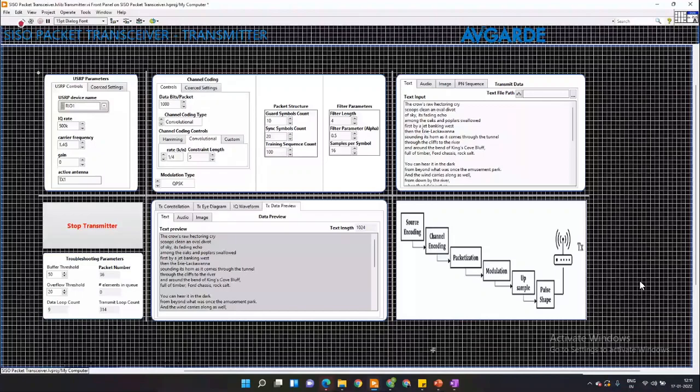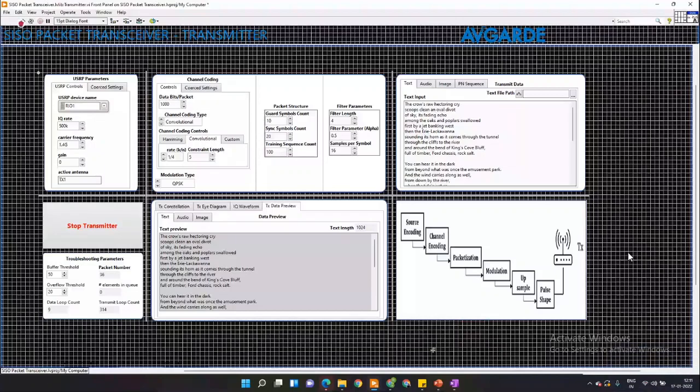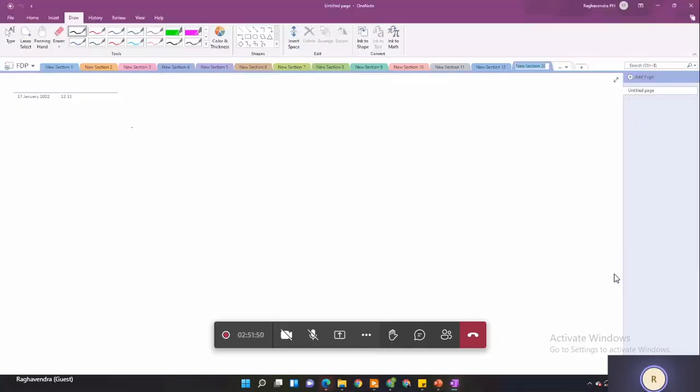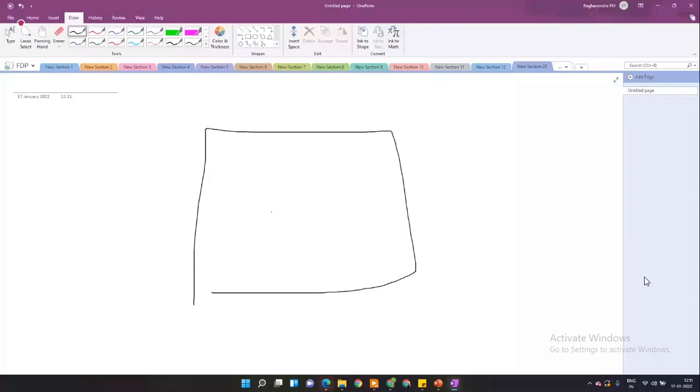Yes, this runs on my PC, correct. Between the PC and USRP, there is a protocol involved called DMA FIFO. I'll take a minute to explain how that works. Your FPGA is actually in charge of communications. Inside your motherboard, you have a CPU, you have something called a memory controller, you have your actual memory location, and then you have a bus that goes to your FPGA.